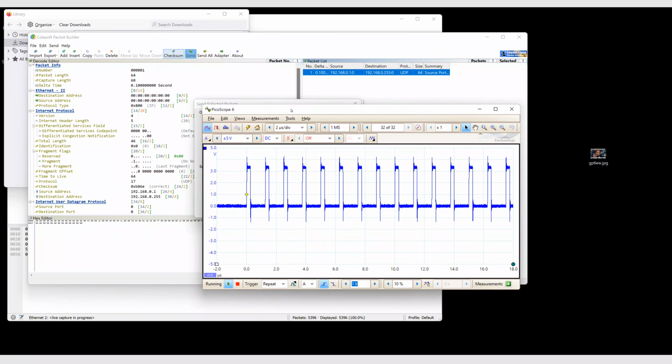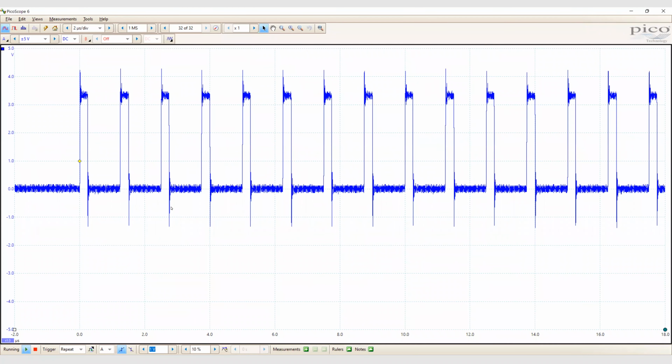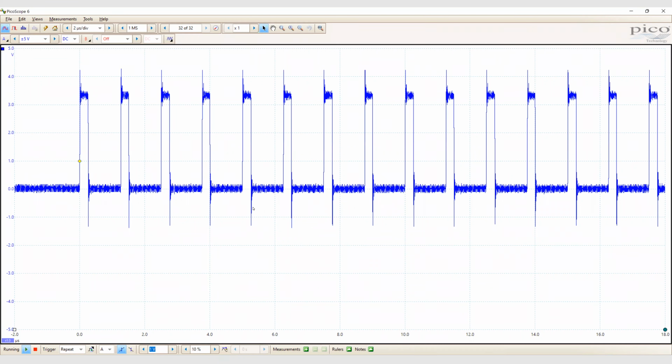Here I have a waveform up on the Pico scope, and I'm connected to the pin. There's only one wire that goes to these LEDs, and the way it works is that there are just pulses that go through all the LEDs, and then they stop. When they stop, they all get loaded in with the color. That's the basic idea. Now, how to do this with the Pico?